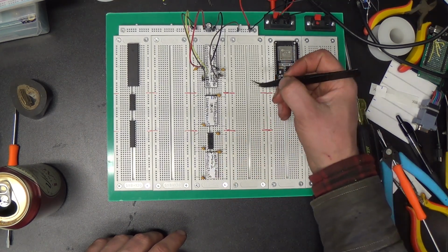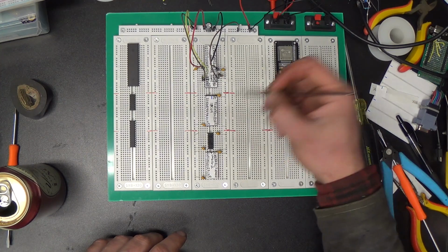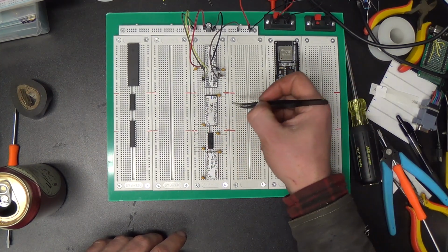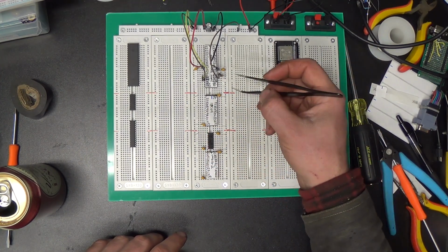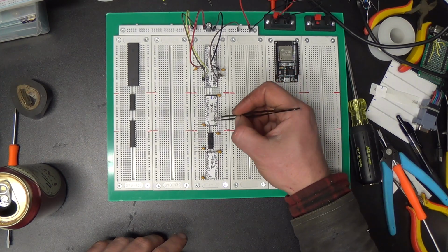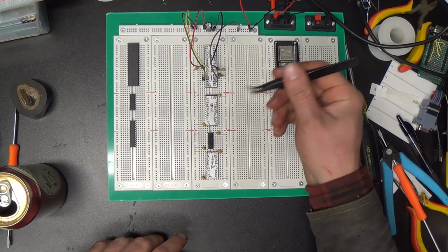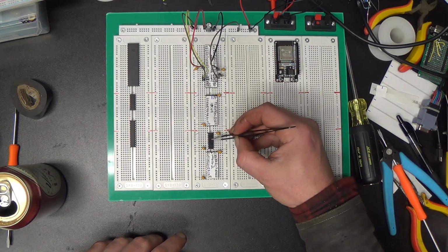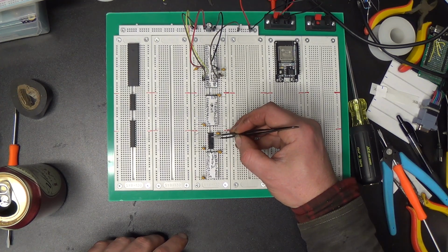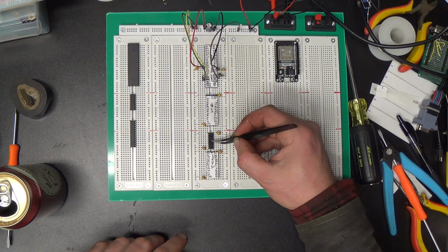We can use compiler directives to tell it where the different memory segments are, the ones that are writable and the ones that are not. I need to do a little more research on that to make things happy. So we're going to do that address decoding with our 74LS00 quad 2-input NAND gate.